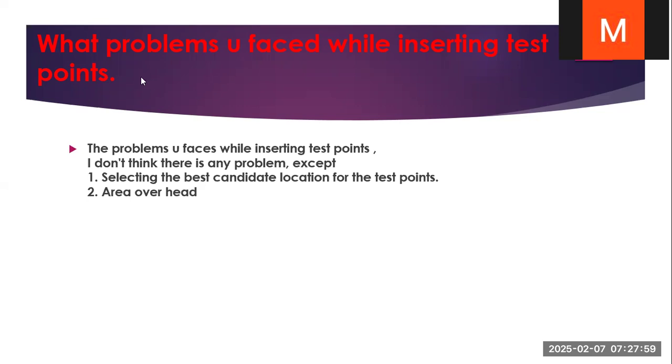My first question is, what problems did you face while inserting a test point? We don't face any problems, but we should keep in mind that selecting the best location for the test point insertion and area overhead are the two major problems we face in test point insertion.